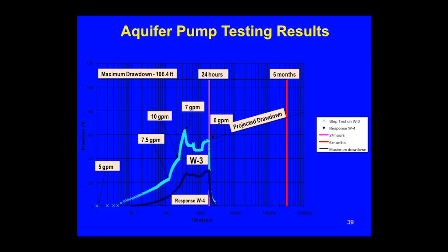But during periods of peak demand, so those couple of weeks in July when it's 95 degrees out for a week or two straight, these systems get more efficient if, as you pump water out of the ground, you reject some water. And the ground's got to make up that water, and make up that water hopefully at the ambient temperature of the earth. And you have to design your system to be able to reject that water, and that's what this pump test does.